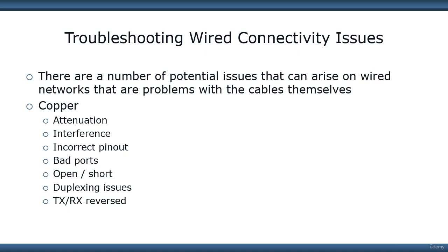You can have interference as well. It would be more with electrical equipment following the wire runs, but that is a possibility. And in some cases, if it's persistent enough, we might need to go with shielded twisted pair.